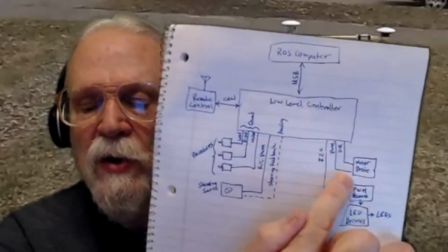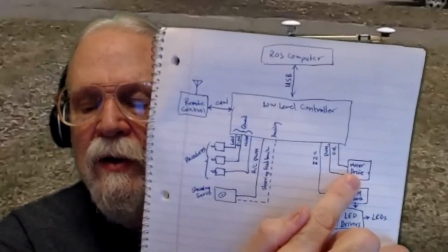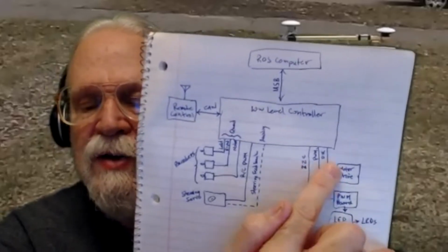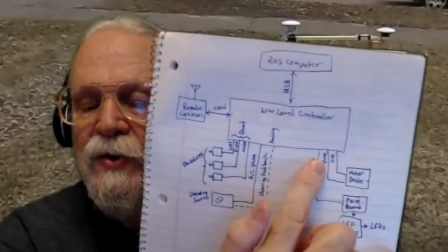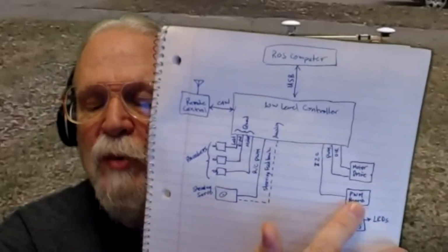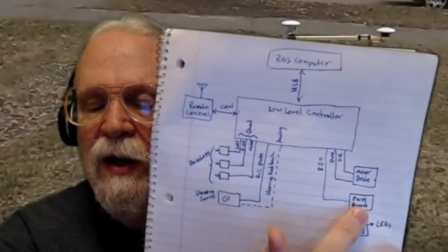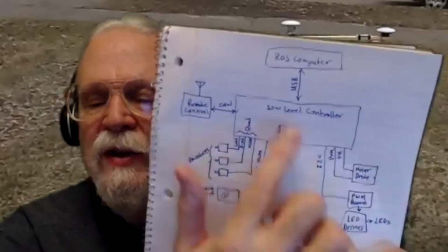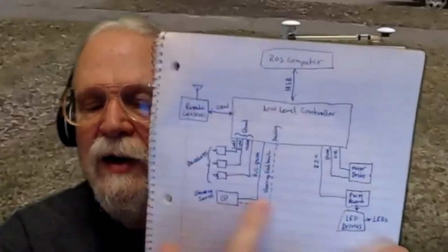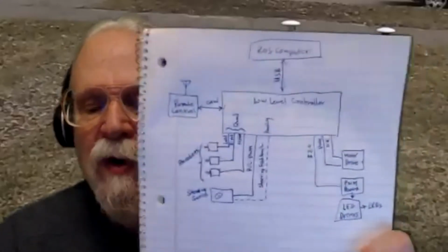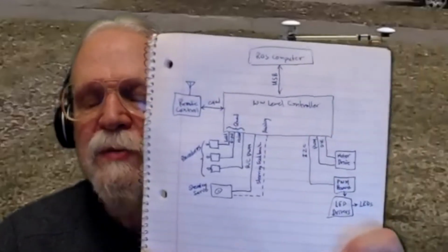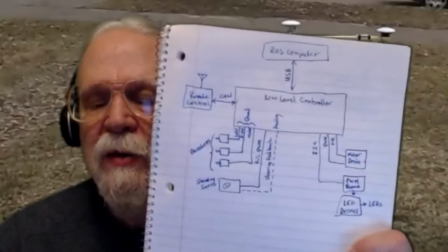And then over here, I've got the motor driver, just like the ones your guys are using on your steering, but I'm using it to drive my main motor in the back. So you've got a direction bit and a PWM bit. Again, those are not communication, those are just control bits. Then down here, I've got that PWM board that runs my flashing lights and everything, and that's just I2C. So it's really mixing two concepts: at the top, the communication interfaces, and down here the control lines. But it gives an overall indication of what's on the vehicle. It seems like that'd be a reasonable step when you're documenting your vehicle.